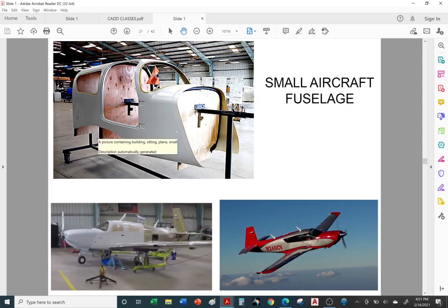I'm not an aerodynamicist, but they would explain, hey, we need you to take these equations. So from here at the crown, from here to here, you're going to use this conic equation. When you were doing graphs of parabolas and hyperbolas back in high school, and you're wondering, where am I ever going to use this? This is where I used it. I was using conic equations, mostly the shape of hyperbolas. In other cases where I worked in other parts, I've used the equations for an ellipse, for a circle, a parabola, hyperbola, or other conic shapes to be able to create the surface.